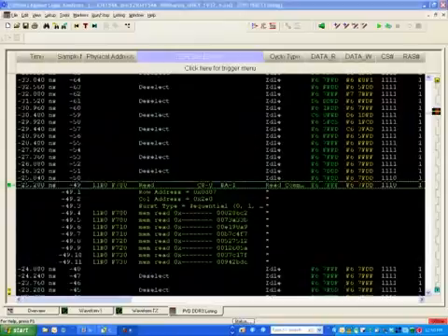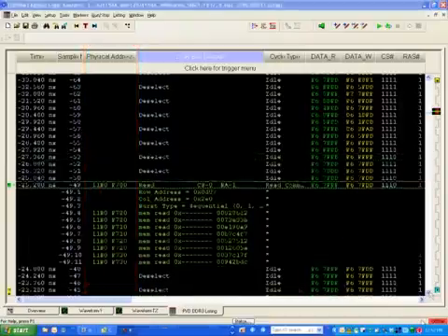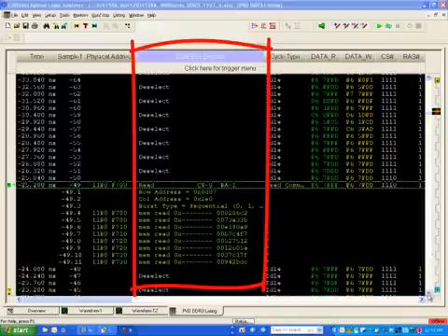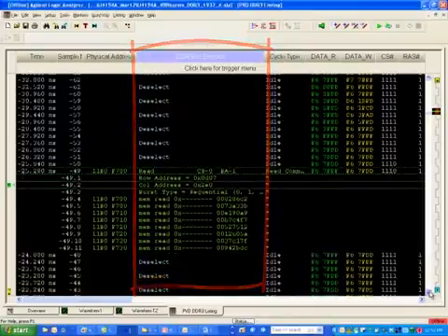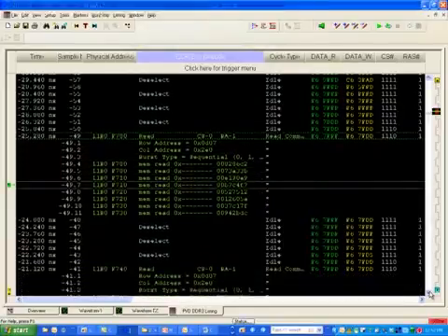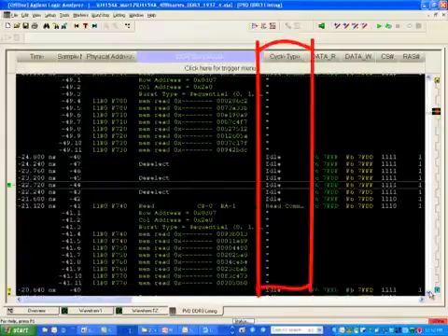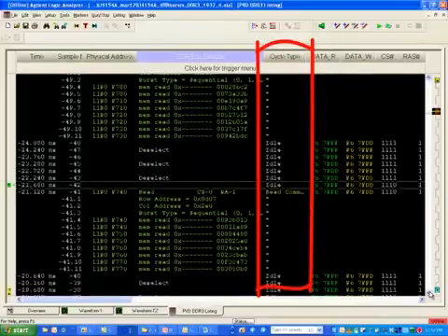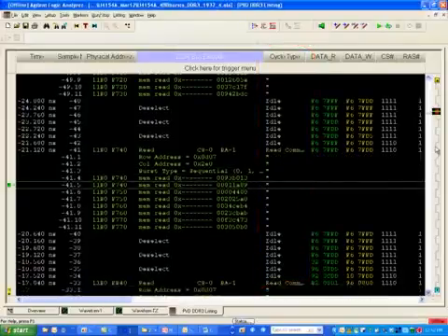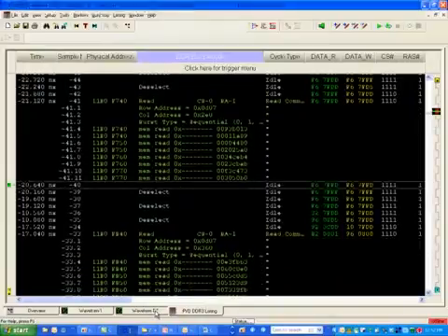In the listing window, we have 3 extra labels created by the decoder: the physical address and the actual DDR bus decode, where the valid read command information includes the row address from the activate, the column address from that actual read or write command, and then the data associated with the command. There's also a cycle type that lets us know what type of command is being executed on that particular sample. We can scroll through the entire listing and see our particular back-to-back burst that was captured and all other data for up to 200 meg deep around the trigger point.